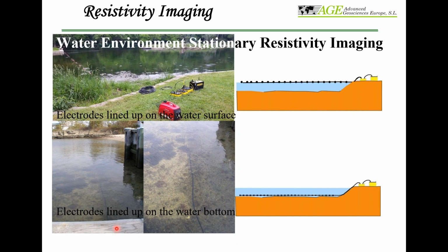and also easy to keep the cable in a straight line. The other thing is you can pull your cable inside the water. With a boat, you pull your cable and then just drop the cable from the boat, and the cable will go through under the water.